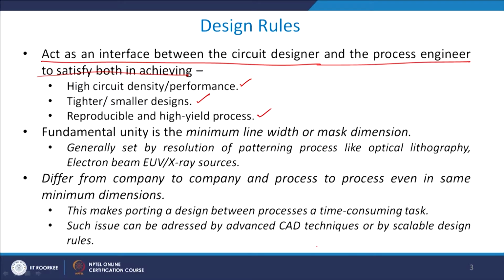Why are they required? They are required because you require a very high performance. For example, if your contact is very large in dimensions, you eat away into area, but if it is very small, you then have larger resistance offered by the contact. So, you need to optimize the contact area, and the process people have already optimized the contact area for you. Say the metal contact should be 0.5 micron by 0.5 micron. They will let you know, and then you design that much exactly onto your profile and you get the best results.